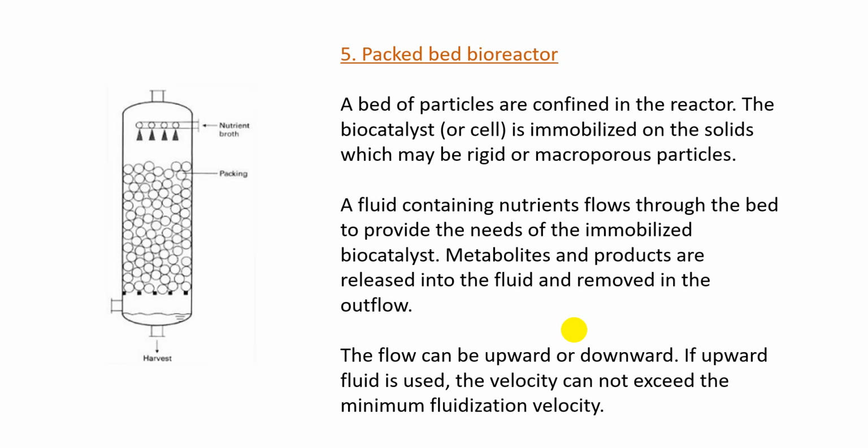Whereas the packed bed bioreactor is a closed vessel having uniform diameter throughout. A fluid containing nutrients flows through the bed to provide the needs of the immobilized biocatalysts, and the metabolites and products are released into the fluid and removed in the outflow.